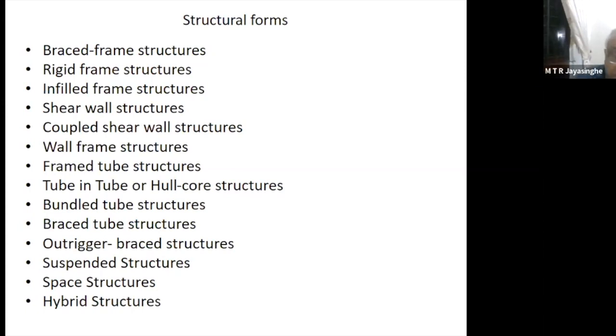So basically, don't do any special moment redistribution because all those different aspects are already taken into account when elastic theory was used to derive those coefficients given in various handbooks and codes. So basically, in design manuals you can find different coefficients, but they are all similar. But if the sizes of the spans are different, then you will end up with all these additional problems.